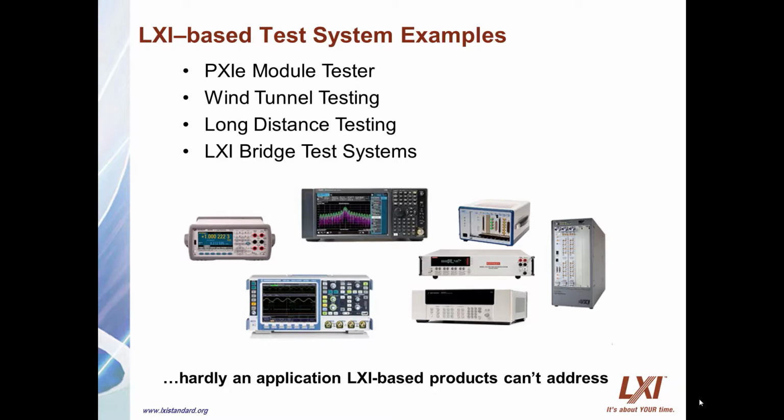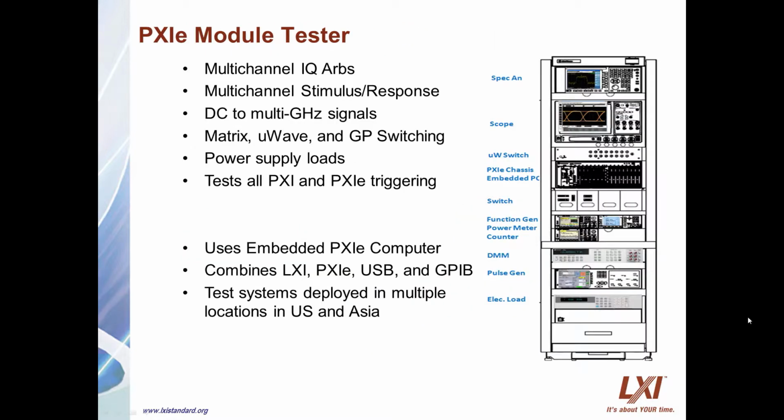Just from these images, you can determine that LXI covers not only proprietary implementations for signal generation, signal measurement, and switching, but you will note the presence of VXI and PXI modules through the use of LXI bridges. This test system has a wide variety of instrumentation used to test various PXIe modules. The PXIe modules operate from DC to multi-gigahertz and must have each of their key specifications verified during production.